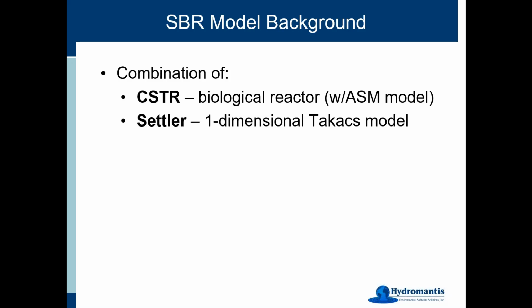This object is unique in the sense that it switches back and forth between being completely mixed and not completely mixed. That allows us to switch between modes where aeration and other things are happening, and then switch over to a layered model. So you have vertical layers like you do in our one-dimension settler models. And of course, all the sludge will settle, and then you can decant and so on.